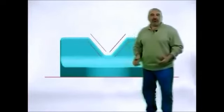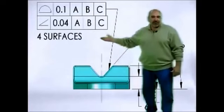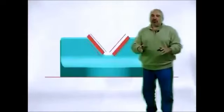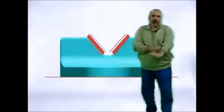If the orientation of these surfaces needs to be better than the orientation provided by profile of a surface, an angularity tolerance may be added as a refinement. Locate first, then refine for orientation second, but only if necessary.